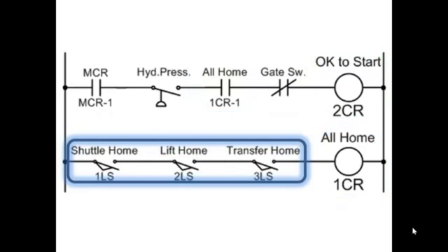Now here's our three limit switches. Limit switches open and close by mechanical contact. Right now, and by the way, they're always drawn in the normal position and they're normally open. They are held open by a spring, and they have a little arm or a roller probe that sticks out, and when they make physical contact with something, it depresses the mechanical device and closes the switch. If the mechanical contact moves away, then the switch is pulled back open by the spring.